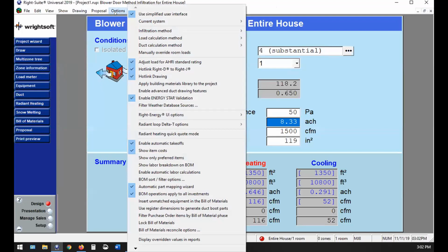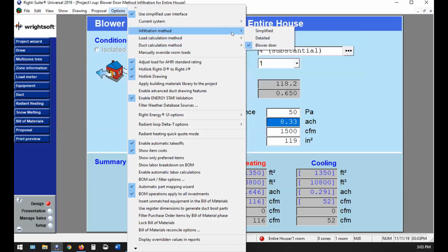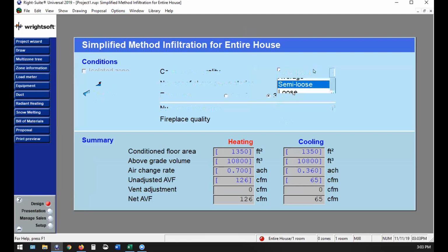It's not a precise measurement. And when somebody is using that term, and they're not just talking generally speaking, I mean, you don't want to be pedantic and just whip somebody with the information you have because they're trying to speak quickly, because it's hard to talk about HVAC equipment without talking about tons. But when you talk about designing a system and you say, this is my load, now how many tons should that be? That's not how it works. The answer is more complicated, and not just for the sake of being complicated. It is actually, and in point of fact, more complicated.